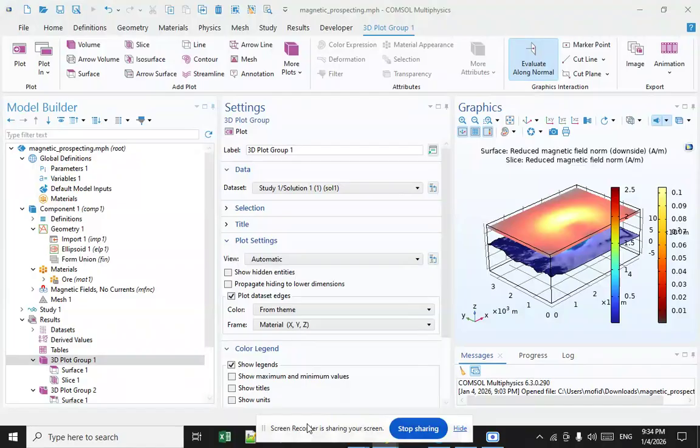Both are towed a sufficient distance, about two ship lengths, away from the ship to allow them to collect data without being affected by the ship's magnetic properties. Surface towed magnetometers allow for a wide range of detection but have lower precision than near bottom magnetometers. The most common type of magnetometer used for marine surveying is the flux gate magnetometer.